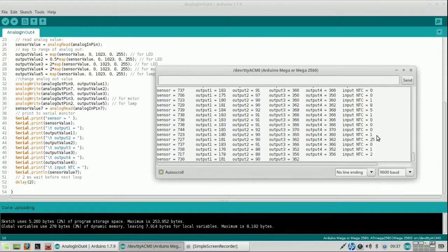So when I change the direction, change the speed of the fan, those values disappear. Well, a value in 10, but most values are very low, which indicate that it should be a high temperature, but that can't be, because the NTC gives low resistance with a high temperature. So let me put down.